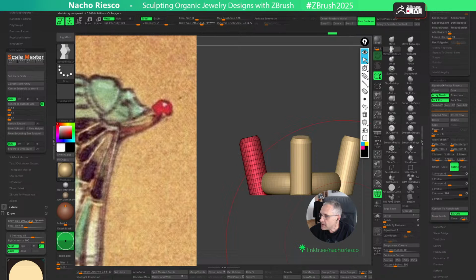My understanding is you 3D print this with a heat-resistant resin and send it to someone that works metal. What I normally do is send it to my 3D printer supplier, which has a 3D printer that uses wax as a master material.